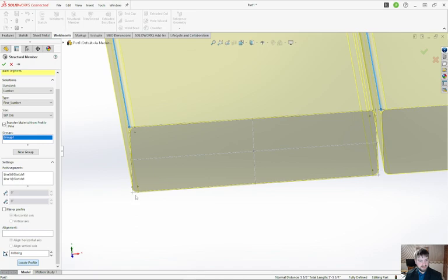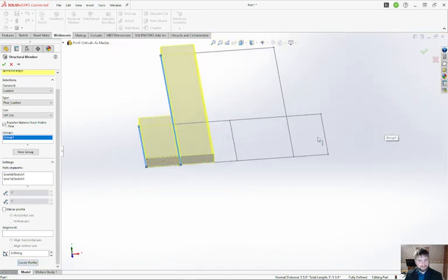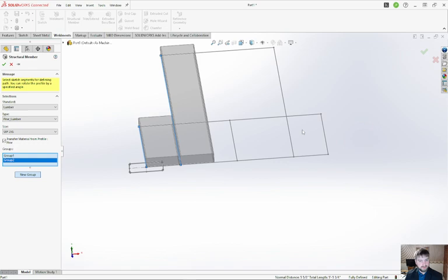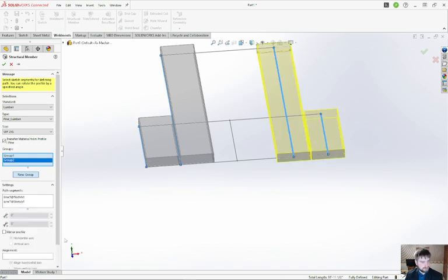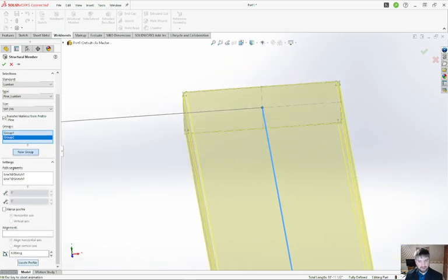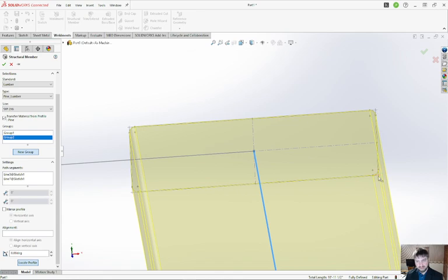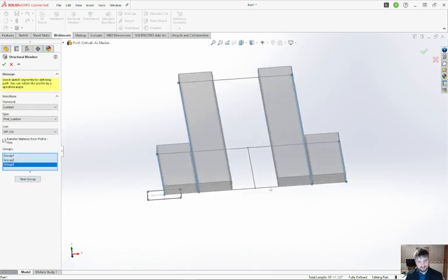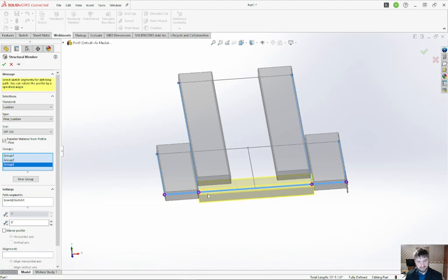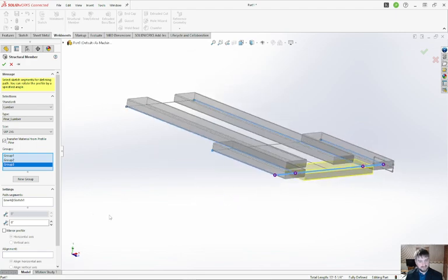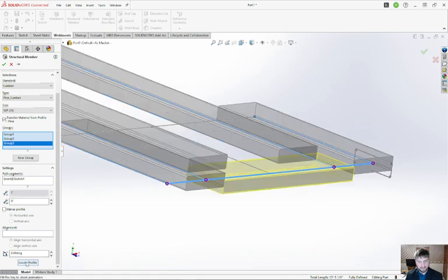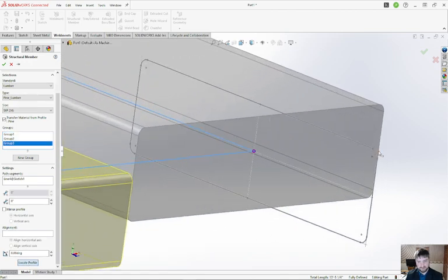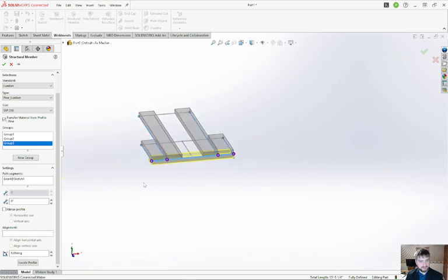As part of this, I can also work intelligently with the program so that as I extrude my lines, they will automatically trim and extend as needed to mate with the other components, like you'll see here in a second. So when I select this line here, as you can see, it automatically trimmed and extended those. But since this runs underneath, when I relocate the profile and put it down, it automatically readjusts it to the correct size.